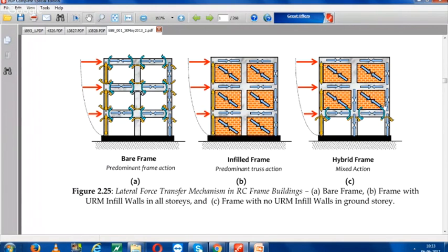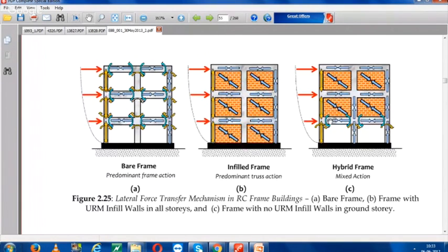In picture 1, plastic hinges form at every junction, every corner point. But in case of soft story, the plastic hinge will form in this region, and this region will behave in a different manner compared to the upper one, so the breakage of column will be there at the junction point, and this story will collapse.